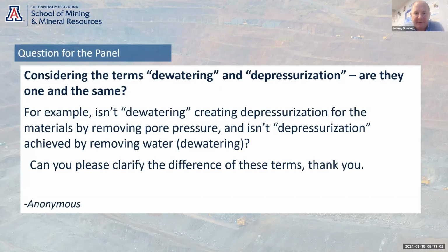So there's a lot of overlap between dewatering and depressurization, but we try to distinguish between situations where we have to deal with very large volumes of water inflow to the mine, which may be disruptive to actual mining operations, and pore pressure in the pit slopes that may be detrimental to slope stability and the geotechnical performance of the slopes. With depressurization, there are many examples where there's actually very little water flow involved. The rock mass may be very poorly permeable or highly compartmentalized, so there's little or no need for the mining operation to deal with dewatering or the removal of large volumes of water.